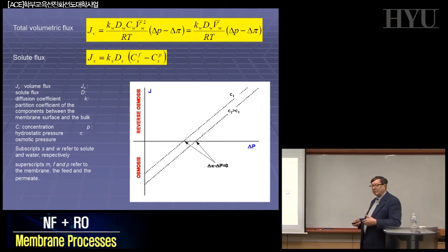And what happens to the salts? The salts accumulate on the membrane surface. That means we are increasing the concentration just on the membrane surface. And so this equation has to be corrected, because this term here is continuously changing. Why do we have this increase of the concentration? Because the convective flux across the membranes is creating the accumulation of the salt that doesn't go through.